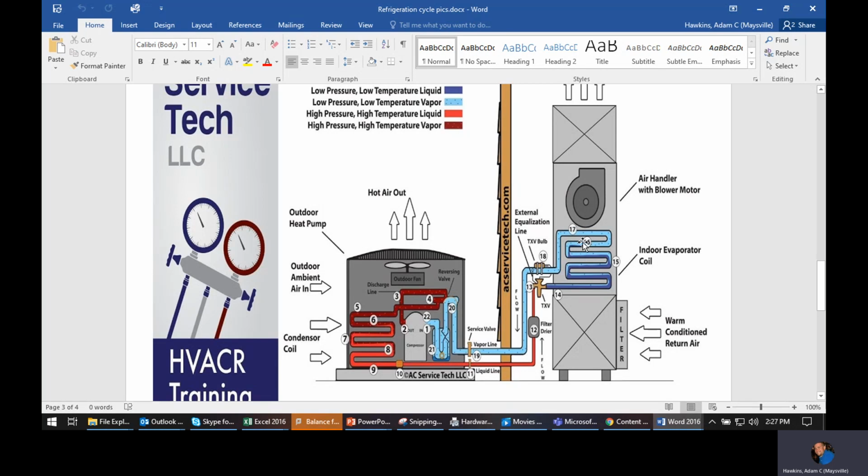So even if I were able to get this coil completely full, that would be better for efficiency, because that would mean all of my coil is doing work. But your system's going to be sized to allow for this superheat anyway. So you've got this extra percentage, and I don't know how much of your coil it'll be, but I'd say it's the last couple of passes through those coils. Maybe the last 5 to 10% is going to be superheat.